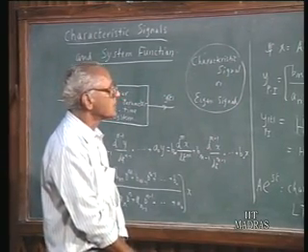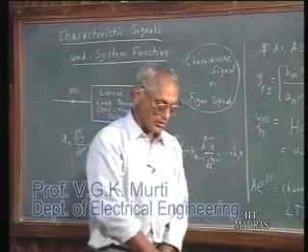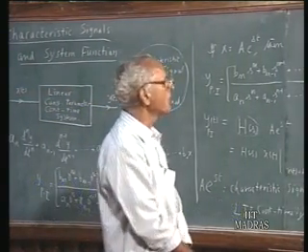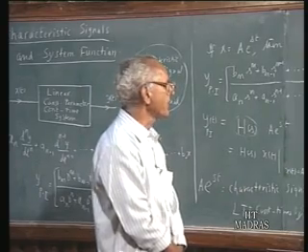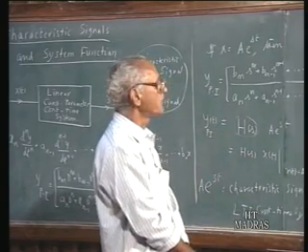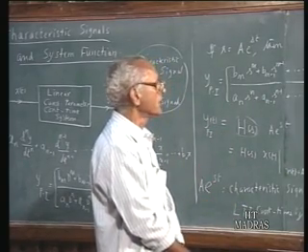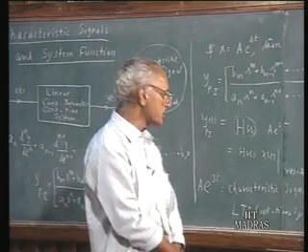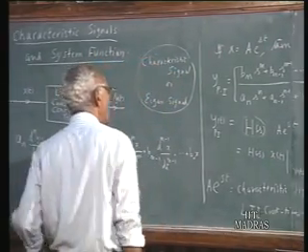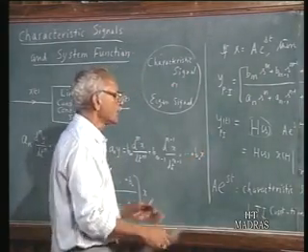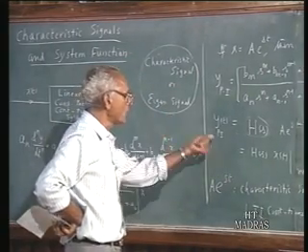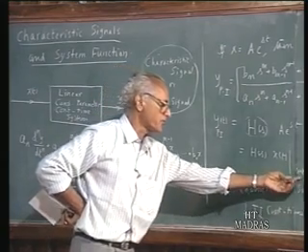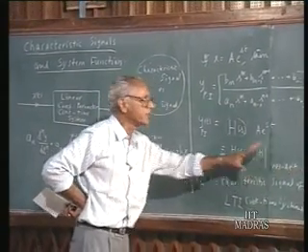Now, the system function plays a very important role in linear system studies, as we will see later, and particularly when you take up Laplace transform techniques. This system function is a very important tool in our analysis of linear systems. But it has nothing to do with Laplace transforms really. We can regard this as the ratio of the forced response to the excitation when the excitation is of the form A e to the power of st. That is all we need to know about it.